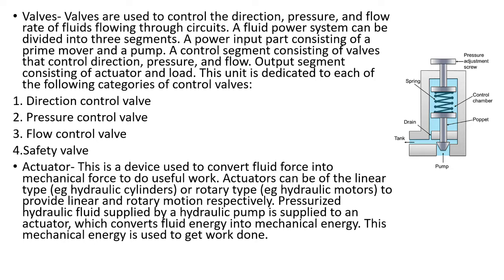Pressure relief valve. These valves are connected at the outlet of the pump. They are a very important component of the simple hydraulic system, as they help in maintaining the pump pressure and the system pressure. If the pump pressure exceeds the system pressure, then pressure relief valve helps in reducing the excess pressure by returning the fluid to the tank. And the next type of valve is flow control valve, which helps in controlling the flow of the fluid. And the last is safety valve, which helps in reducing the negative pressure in the actuator, which develops due to the external force, by returning the fluid to the tank.